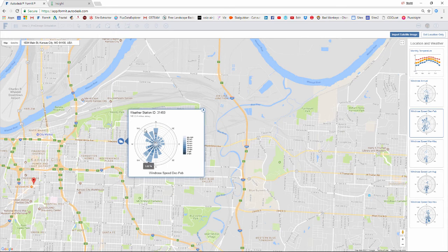And unfortunately, it's coming primarily from everywhere, but the strongest, most vile bits of wind are coming from the south-southwest and north-northwest. So this north-south wind is sort of blasting the site. And so if I can work the building to help block that, especially when we think about entries into buildings, that might be really, really to my advantage.